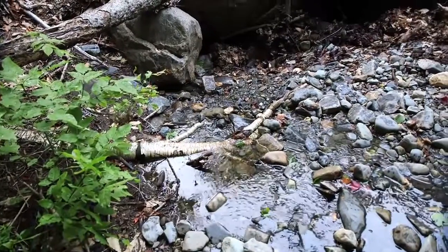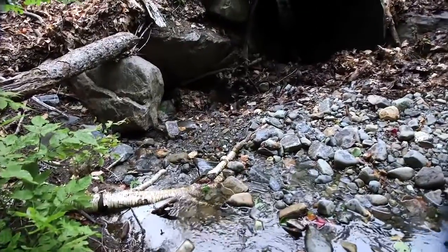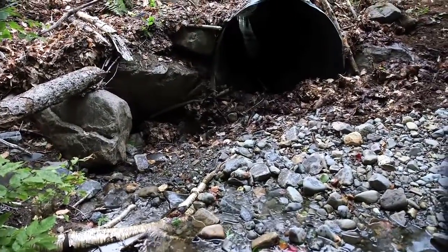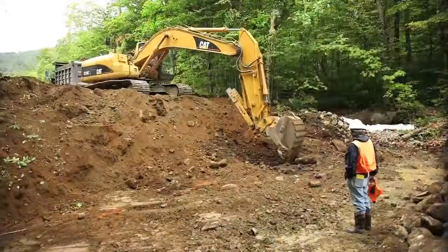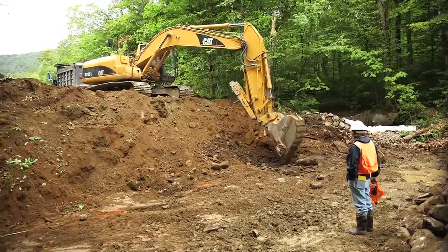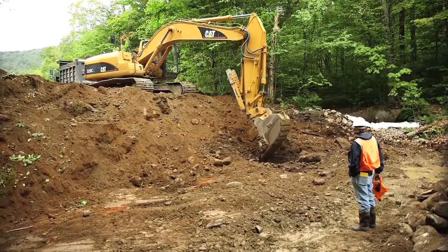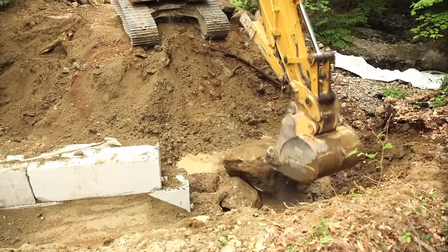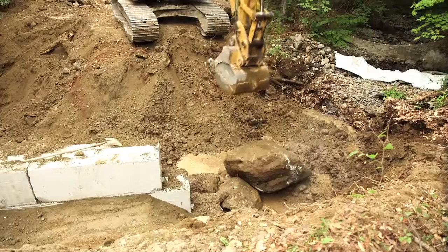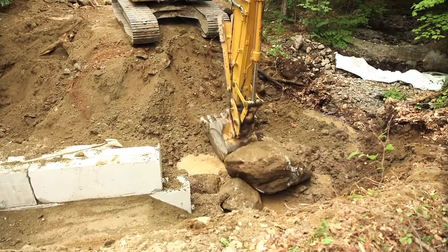Water control. Water control typically consists of diverting all existing stream flow around the working area of the construction site. Any groundwater encountered in the working area of the site that picks up any sediment or is dirty water is pumped from the site and run through some type of sediment basin before the water is returned to the stream.